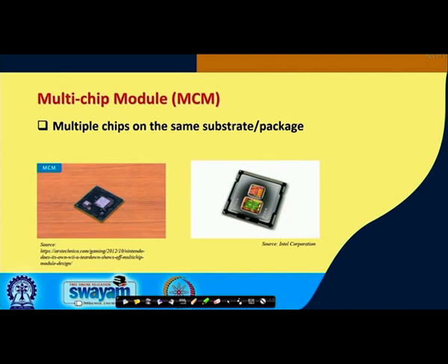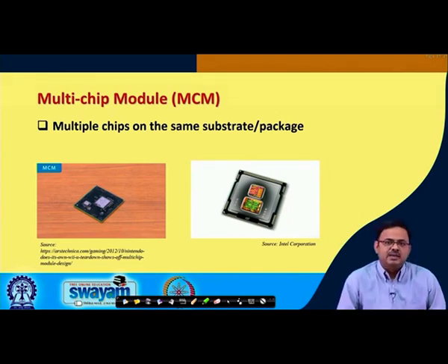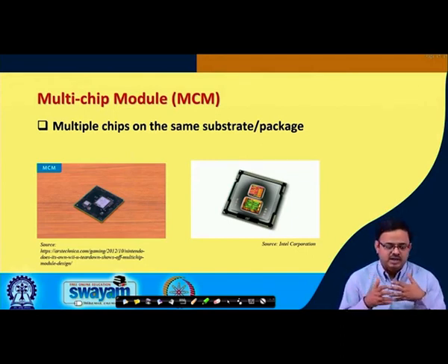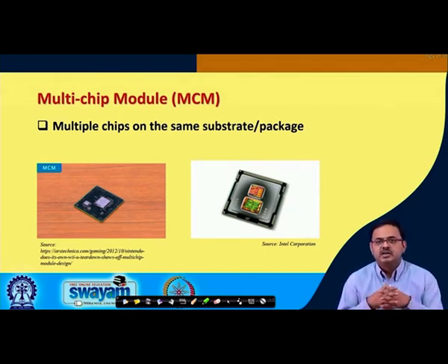The first one is the Wii, a gaming device from Nintendo, and you see that there are two pieces of silicon. The ones you see in gray are a real picture, a real package with 2 important components on the same package, and the interconnections between these 2 components are through the wiring layers in this substrate, which is an organic substrate, FR4, and that is what we see there.